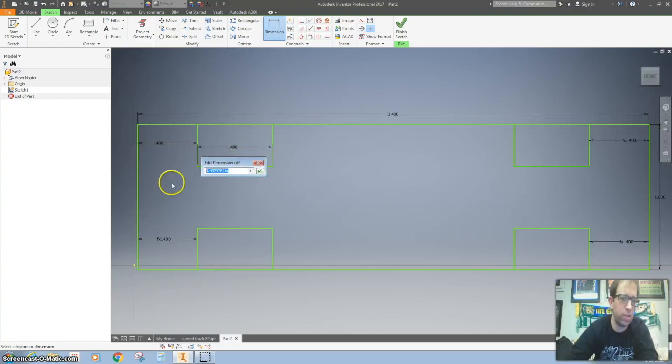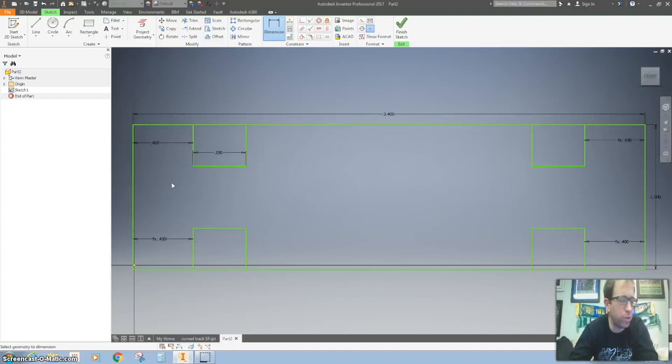Okay, here we go. Let's change this right here. The width of that, 0.75 minus 0.4, which is 0.35, equaling the height on this is 0.1875. I changed it on all of them. Just to make sure my constraints are turned on, I can hit F8. It shows me all my constraints. Got them all there. F9 turns that off.